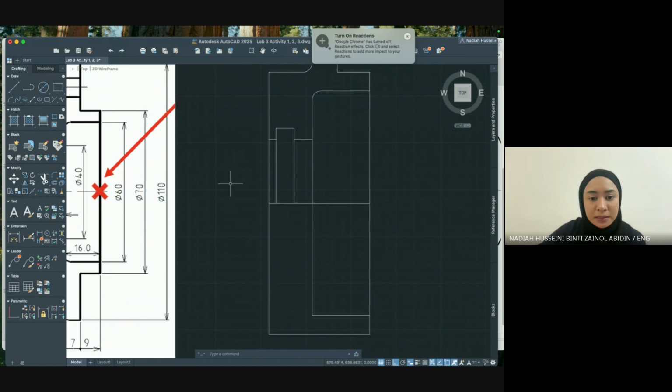Okay, from the center line, this is my pretend center line because I want my dimensions to be hidden, and I don't want to do the dimension now. I'm going to do it later. So going up by 28, and then going to the right by 7, and then I'm just going to extend this bit like that.